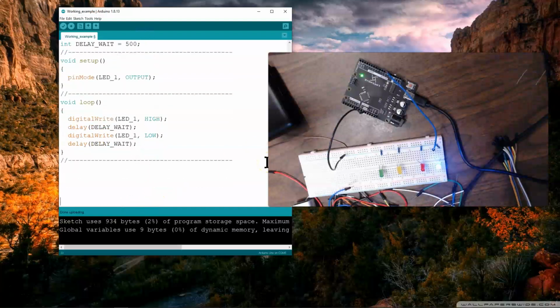I'm going to add a new function now. I want a function that I'll call to do a delay. I know that the code we have in the loop right now, given a pin and a delay time, will delay for a specific amount. So let's make a generic function that will blink 1 light. It doesn't need to return anything, so I'm going to give it a return type of void.